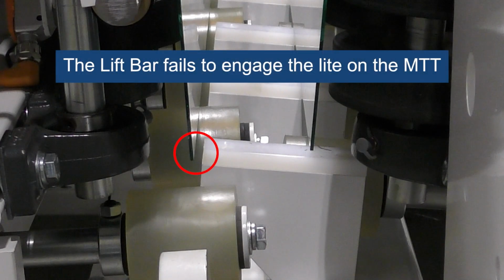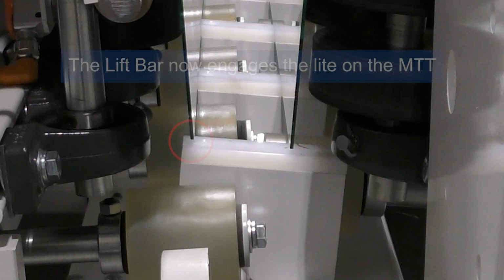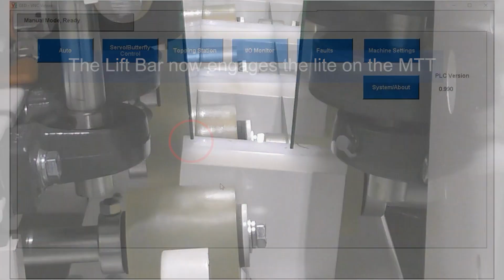As you see here, the table is not shifted over far enough for the lift bar to be completely under both lights. Now the shift cylinder has been positioned so the lift bar is just barely under the unit on the moving tilt table. The current position of the shift cylinder is the value that should now be entered into the min butterfly set down position parameter.